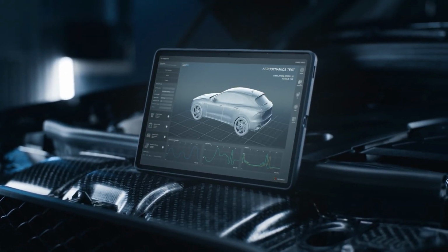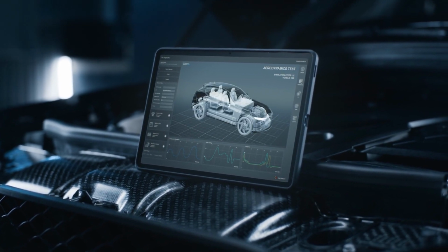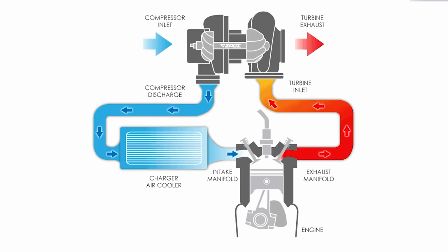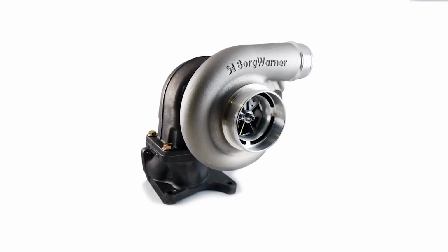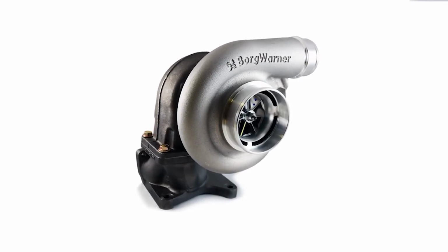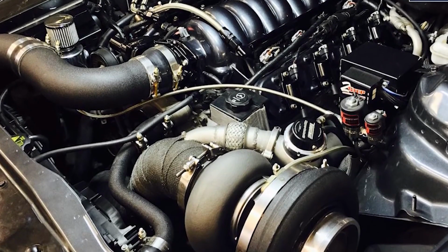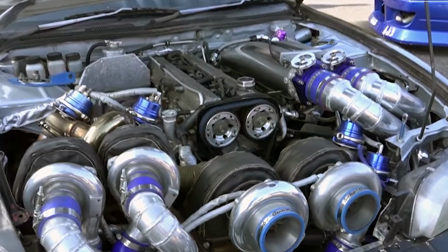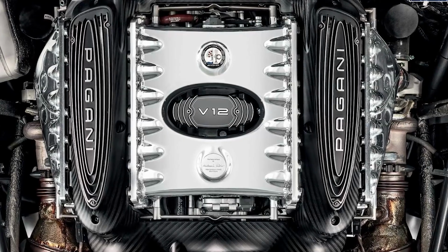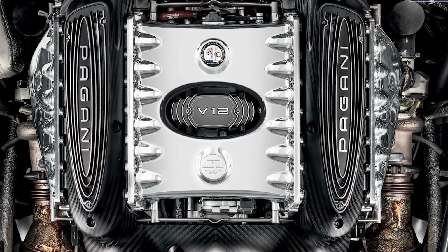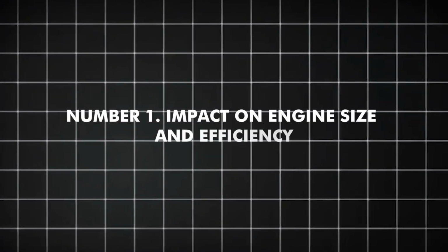Some CHRAs are water-cooled to reduce the temperature of lubricating oil, preventing oil breakdown and increasing durability. Seals on both the turbine and compressor sides prevent leakage of oil, exhaust gases, and intake air. The precision engineering and specialized materials enable the turbocharger to maintain reliable, high-speed operation while enduring stresses from thermal cycling and mechanical loading.